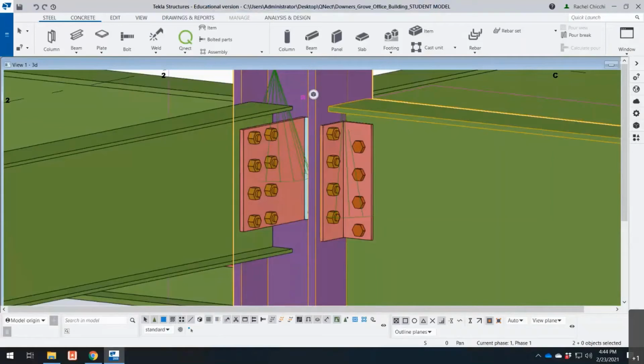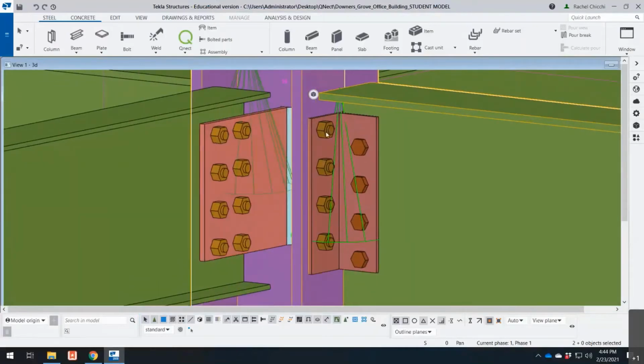If we go back to the Tekla model, you'll see that bolts may be staggered as shown in this connection. There's a vertical offset between the bolts in the column versus the bolts in the beam. This is often done for entering or tightening clearances. The shop installed bolts that are on the beam may interfere with the field installed bolts connected to the column. This is especially an issue with tension controlled or TC bolts that have longer ends that need to be sheared